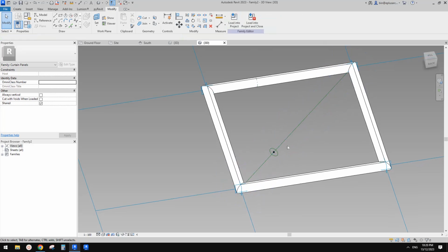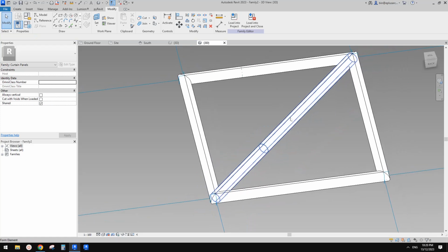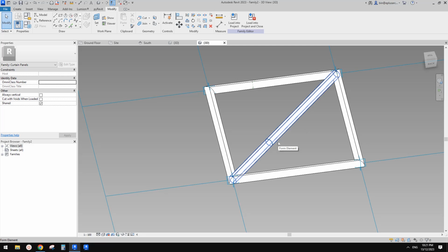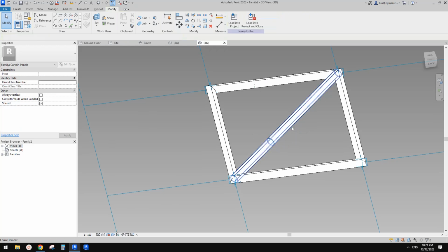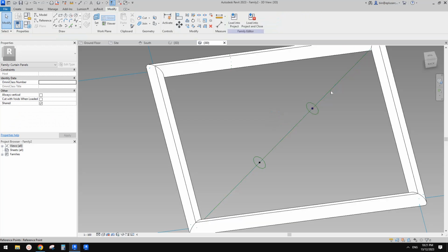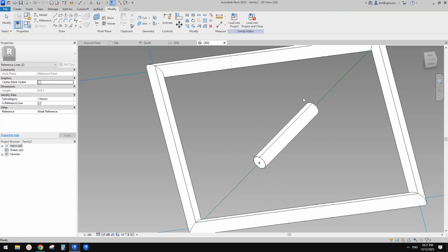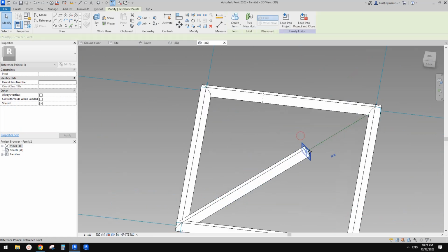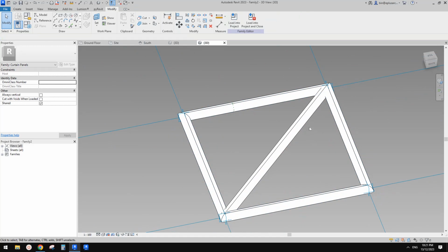new host. Okay, so here I think if we create this one, sometimes it might cause issue, because if you use one profile with a path, and then sometimes when you have some organic shape and some special geometry, it will break. Okay, so when that happens, you can just create another one. So instead of use one profile and a path, so just use 2 profiles. So this will fix that issue. So okay, so yeah, and this is it.